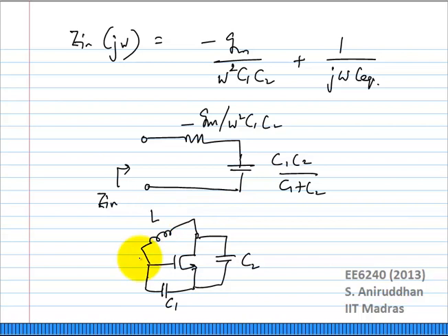So what do you know? If I call these the oscillation nodes A, B, two things you know. If you were to represent this as a, you can easily decompose this into a parallel equivalent circuit, right? What you do know is that the negative resistance should be less than or equal to the positive resistance if you look at them in parallel.